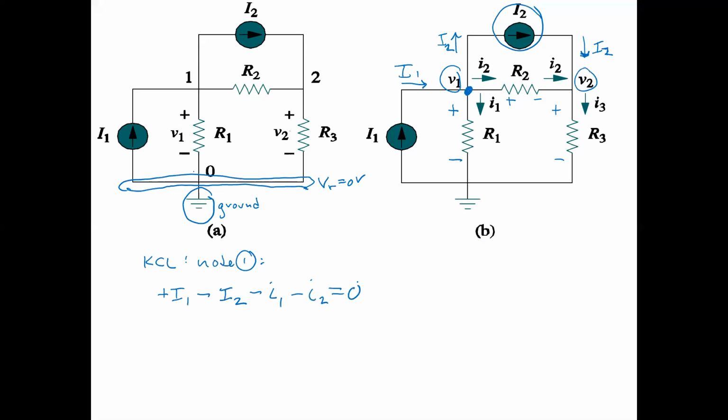So you can go through those steps, but once you get the hang of doing nodal analysis, you can skip labeling the little I1s and the little I2s, because you can do those by inspection. It's really easy using nodal analysis, and once you get good at it, you'll see how easy it is. It's going to be I1 minus I2. Those are given to us as some value.